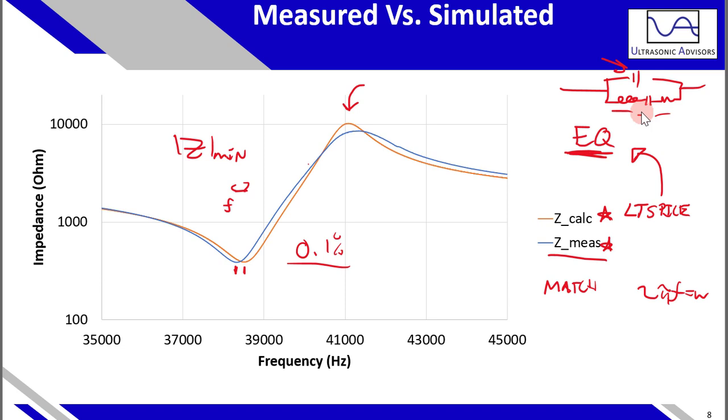The other thing to note is, just like we talked about a quality factor for the resonant frequency, when we use the real admittance, there's also a quality factor A, which is of the anti-resonant frequency, and for that you can use the real impedance.